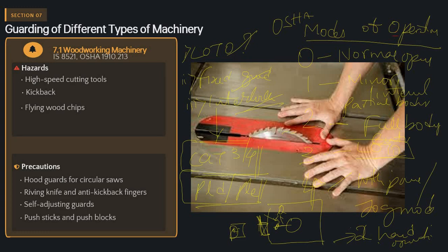In mode 4, we need to carry out the work under utmost supervision. If you are using jog mode, we should use a two-hand control operated jog, and the speed should be low. Any doubts? This is a very big subject, but this was brief.